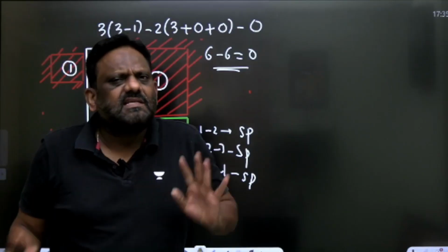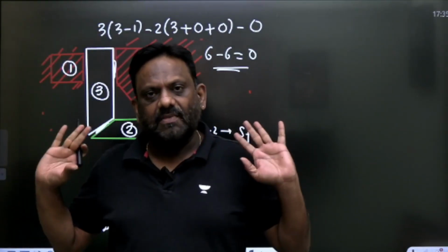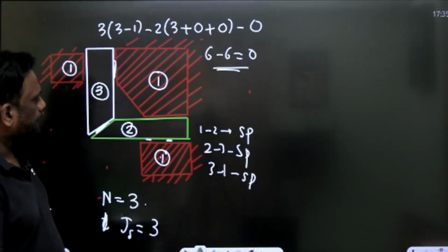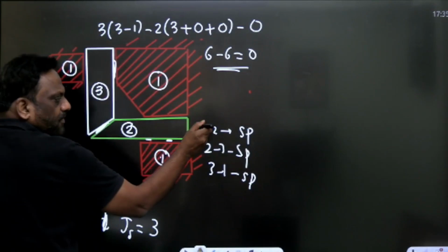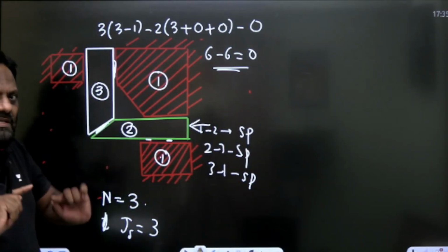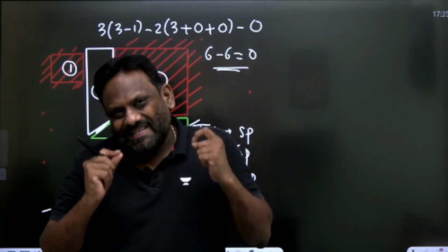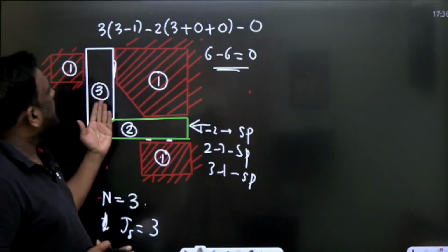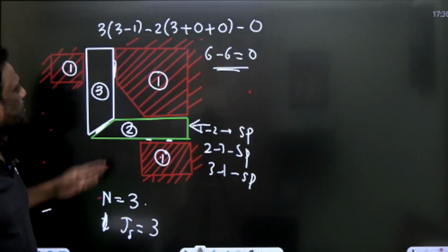What does it mean? It's a structure, meaning there is no relative motion between elements or links. So this should not move. But actually, if you observe, if I give some input, say I push this link 2 from the left, definitely this will move up. It means there is a one-to-one correspondence. So the degree of freedom is 1. It is a constrained mechanism. So there is clarity: if I give one input, there is one output. Definitely if I push this in the horizontal direction, there is a motion.